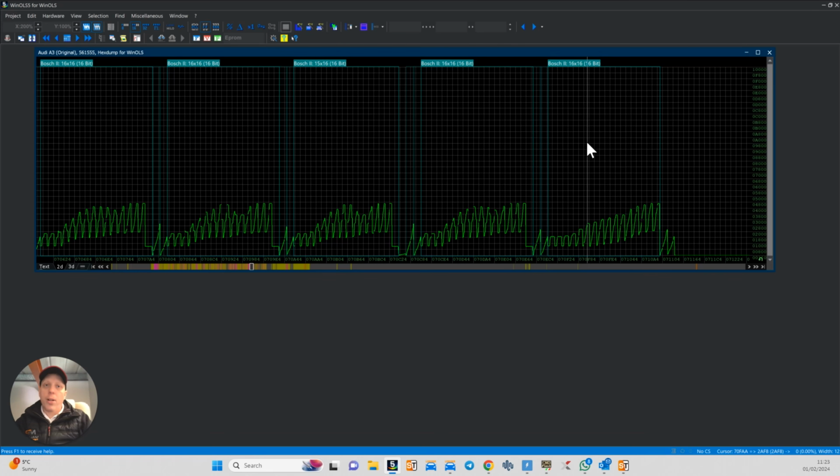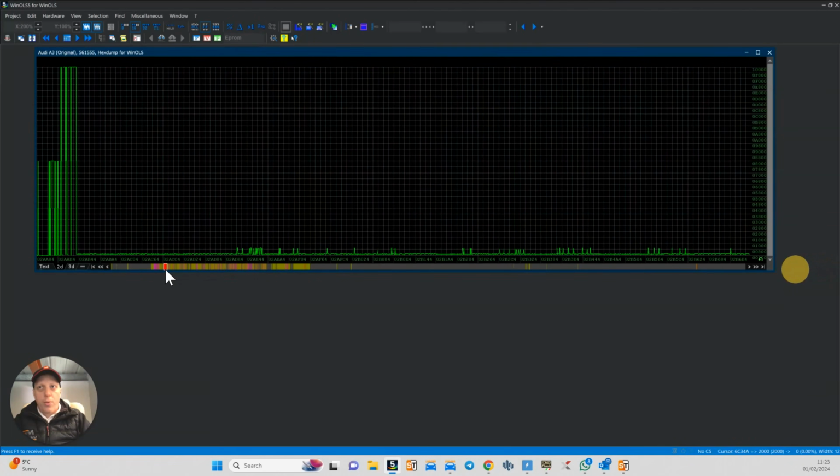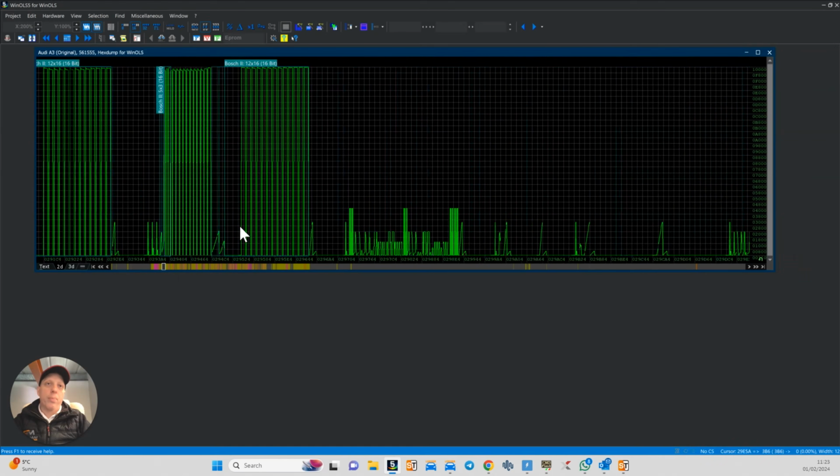This is pretty much how it works. Then you've got fail safes. If the ECU got it wrong and you overboost because of the settings that we've left in the ECU, then you've got all the settings that are going to drop the car into limp mode based on those requests. So there's quite a bit going on when you're tuning these cars, which is why everyone needs to be logging it and seeing what's going on.